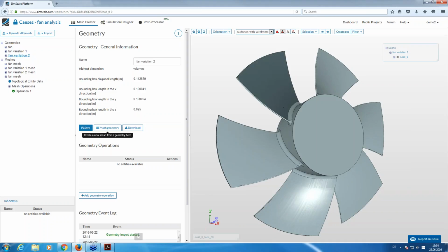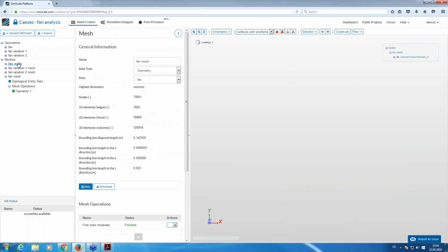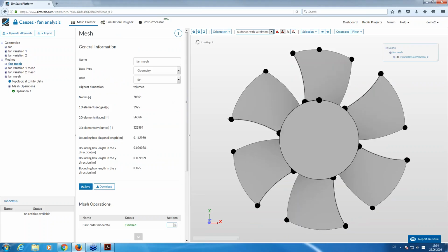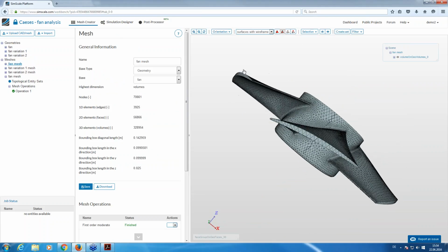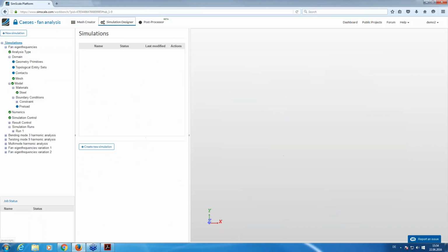You also know that from materials that are stiffer, if you now hit them and see the vibration, it will be at a higher frequency. Okay, so what we now need to do is simply start this mesh, and what we will get is a mesh that looks exactly like this here. This is now a volume mesh, and based on the nodes of this mesh, we can start a finite element analysis.